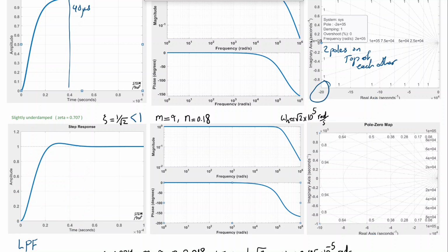Okay, so in the frequency response, you can see that omega n is further down from 200,000 to about 140,000 radian per second. And now the poles are shifting outward. The poles used to be completely real. Now they are moving outward as complex poles, and they are now at 100,000 radian per second.